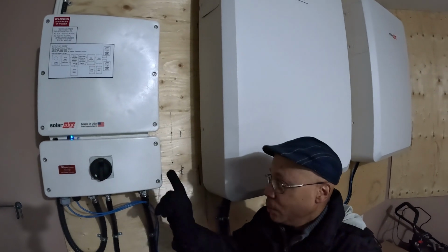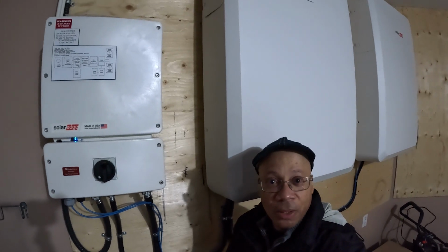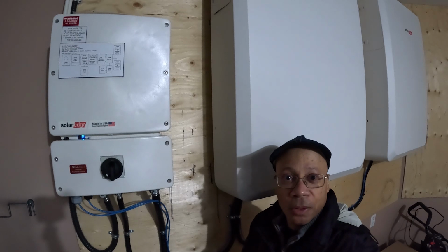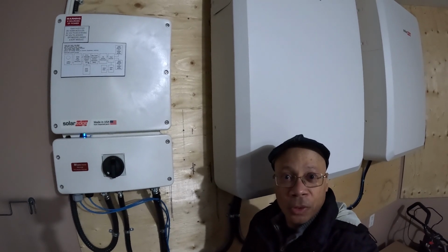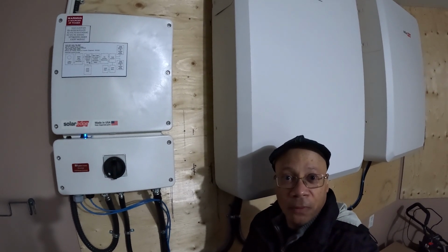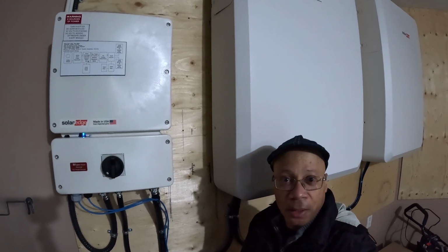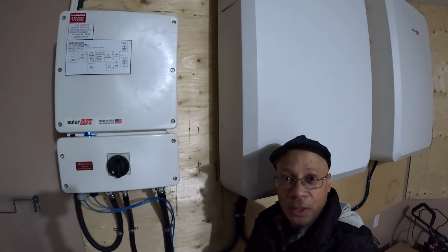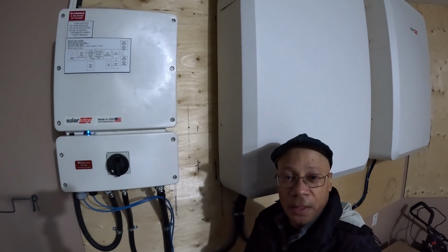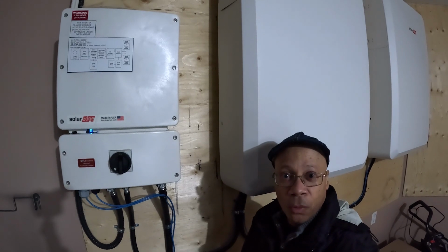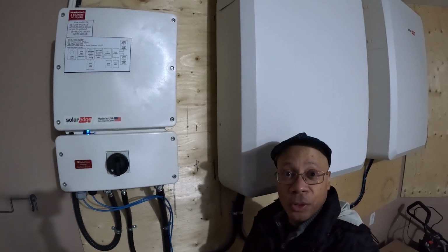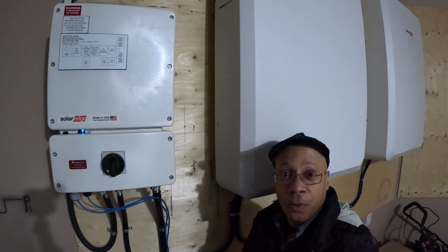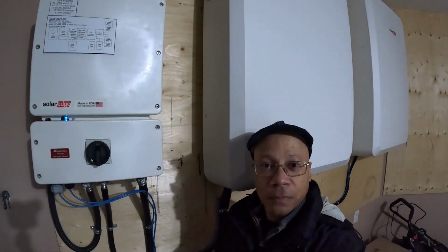And connected to my inverter are 28 roof-mounted 425 watt solar panels for a total rated power of 11.9 kilowatt peak. And also, in my specific case, 28 SolarEdge DC optimizers were installed, one per panel, in order to maximize the power production of each panel and allow for panel level monitoring.